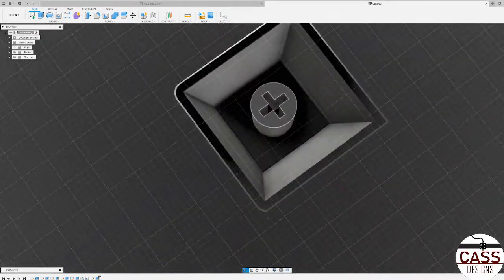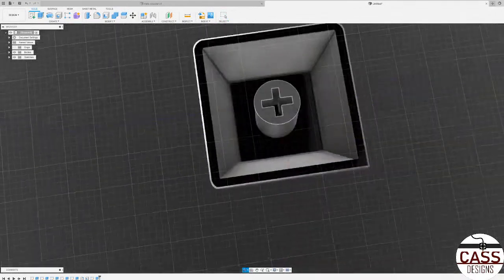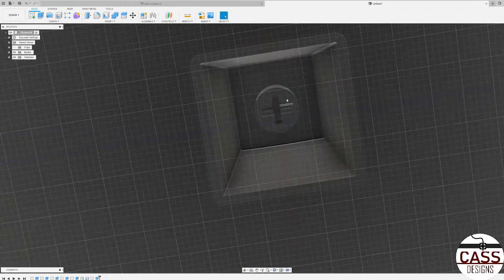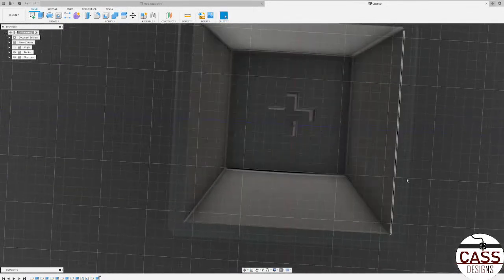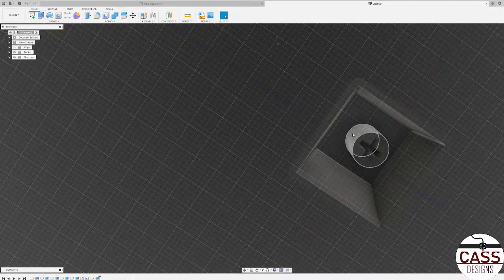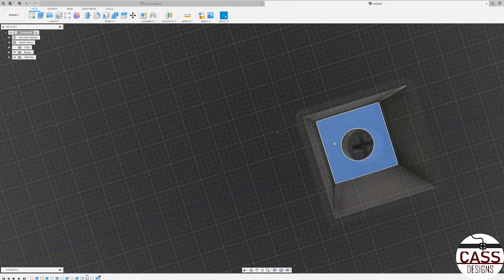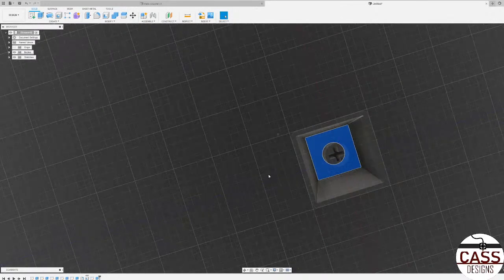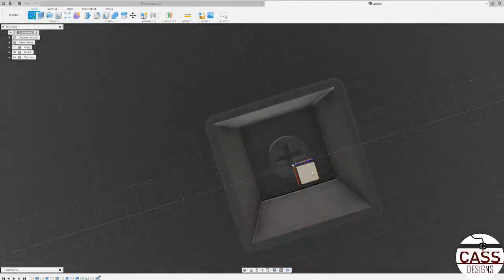And then one last thing we can do, that we don't really need to, but what I did in one of my designs is I added a structural reinforcement that attaches to the cylinder that goes over here. What you do there is you grab this surface, you create a sketch, and you can extrude another rectangle, and then fill it in between. I'll show you. I'll do one real quick.